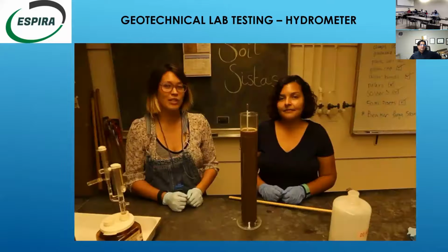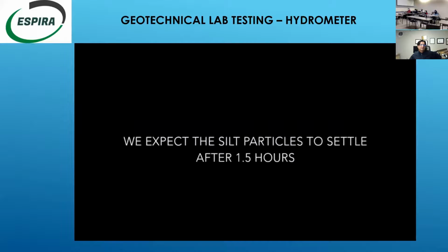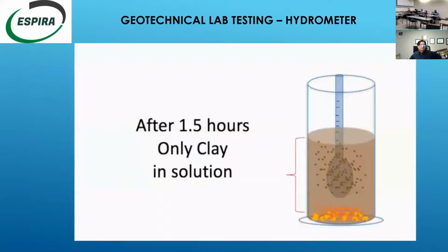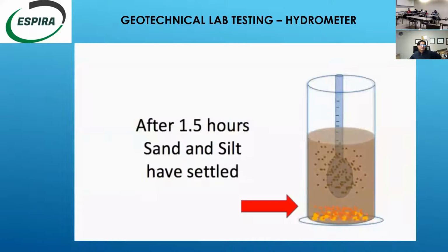Our next reading is at 1.5 hours. So we'll see you at 1.5 hours. So it's been 1.5 hours. What we expect to be suspended is the clay, whereas the silt and all the sand particles have settled.